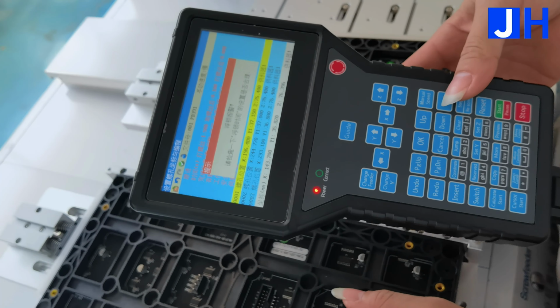We select time settings, click to open, and modify the parameters to 0.2. This means that if the screws are assembled within 0.2 seconds, an alarm will be triggered. Select the coordinates and click single step. Now it works, the screws are assembled and no alarm occurs.